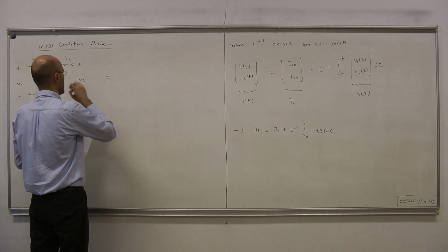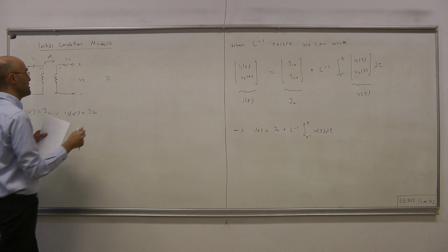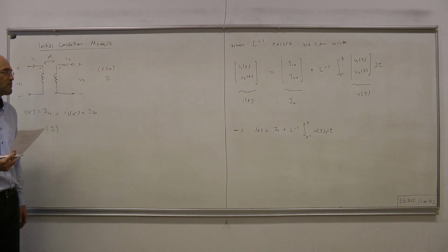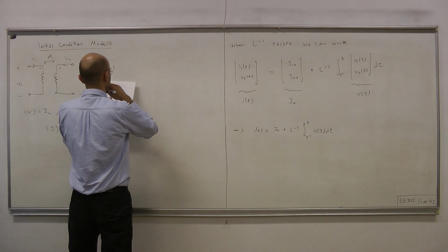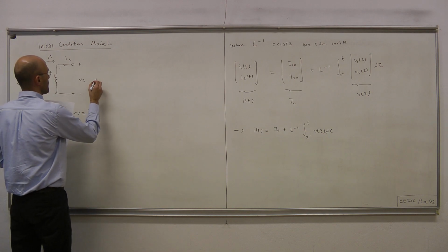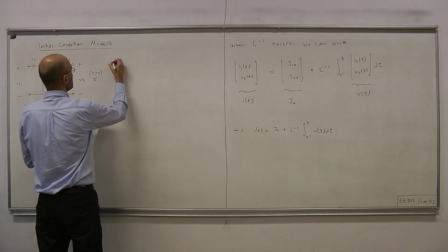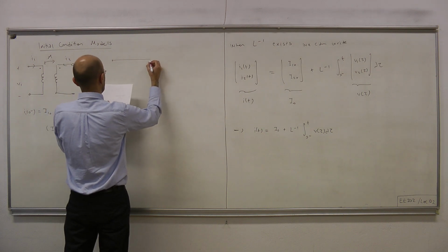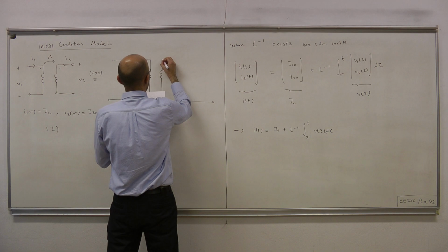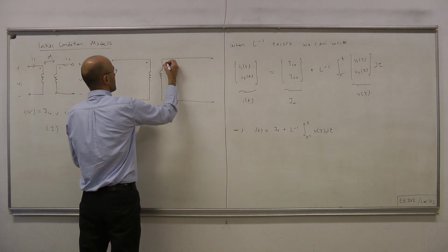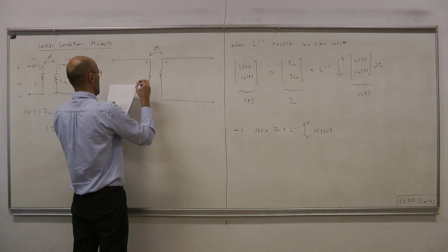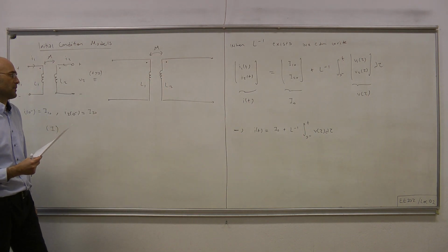One way to do that is the following. We say this 4-terminal device is equivalent, from the point of view of voltage-current characteristics, for all positive times to the following two other configurations. First configuration, equivalent for t positive: again we have a pair of coupled inductors, and the parameters L1, L2 and also the mutual inductance are the same.